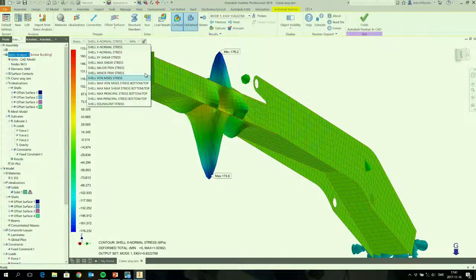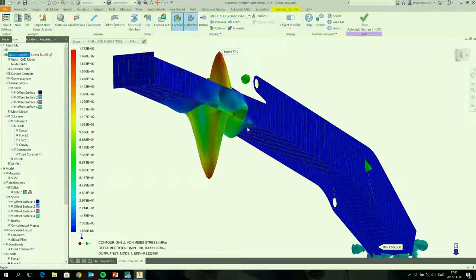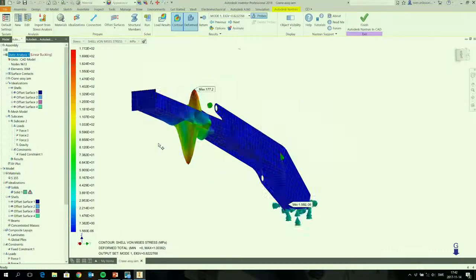You can only compare it within the model. So you can say if I light the probe and if I look here, if I have like 1.8 here and 1.72. No, you can't use the values. Only look at the modes, the mode number, in which levels. So what I'm saying here is it will buckle at 0.82. And that is a problem. You can't make a lifting device that buckles below the limit load or the intended load.